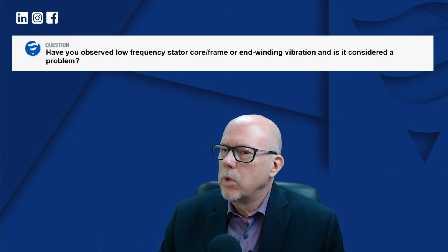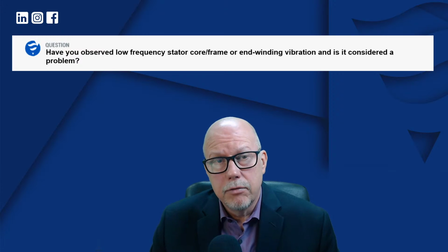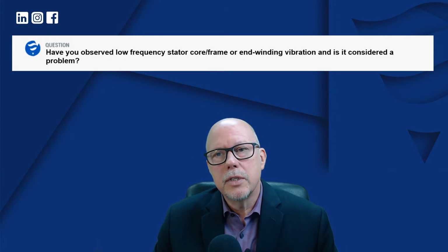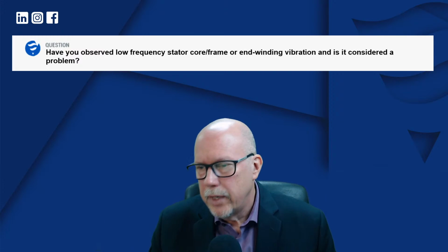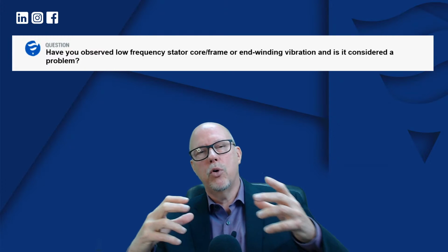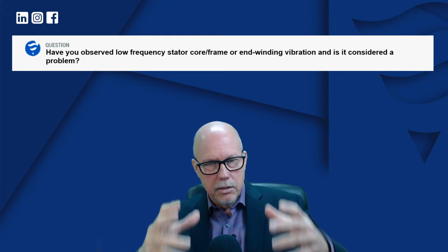And what they decided to do at some point is to install a sensor on the end core, on the core itself. And lo and behold, they noticed that the core was showing the same thing. So to make a long story short, in reality, the end windings were not vibrating as opposed to the core. The whole thing was banging against the foundation.